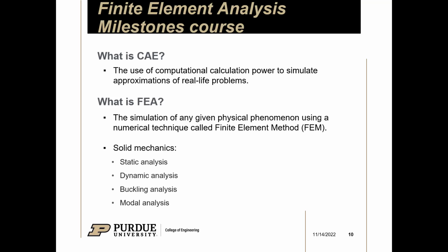It's just extremely long and tedious for an object like the one we will use as an example, and it's much easier to use a computer. You can do static analysis, which is the one we'll mainly focus on, dynamic analysis, where loads are changing, buckling analysis, where there's deformation going on during the application of the force, and modal analysis as well.